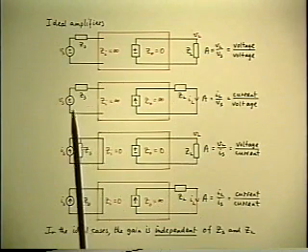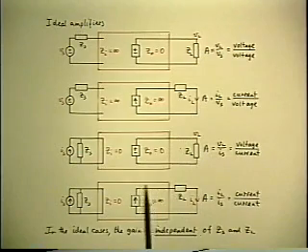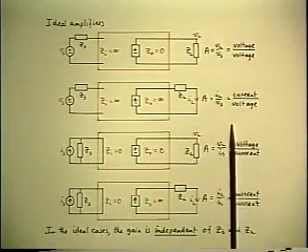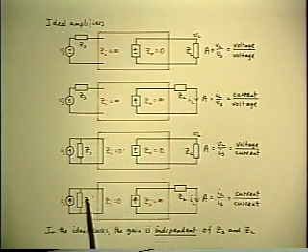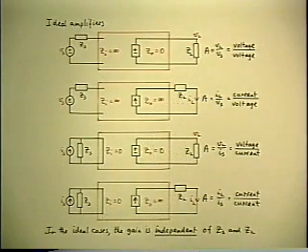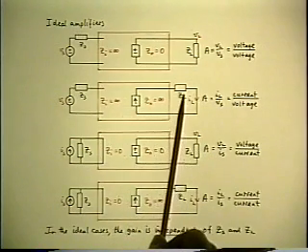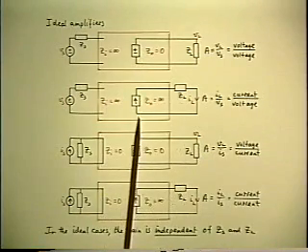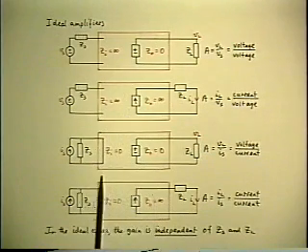And likewise for the other ones. If the output signal is defined as a current, Il, then you would want the gain Il over Vs, which is a transadmittance, to be independent of Zs and Zl. And again, the input impedance would have to be infinite, but this time the output impedance would have to be infinite also, in order for the output current to be independent of load. In other words, you'd need an ideal current generator at the output with infinite impedance.